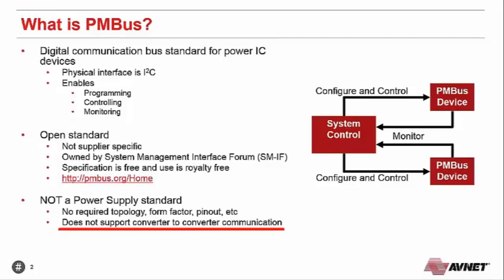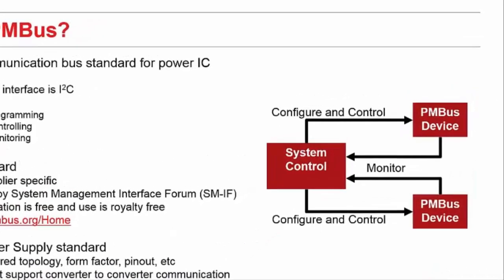Another thing to note is that it does not support converter to converter communication. Communication structure is such that you have a system control that can talk to all the different PMBus devices, but the PMBus devices cannot talk to each other directly.